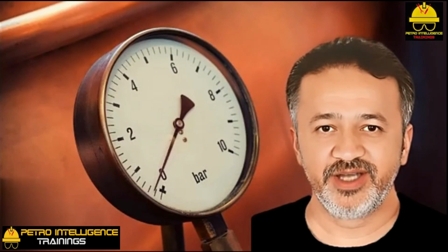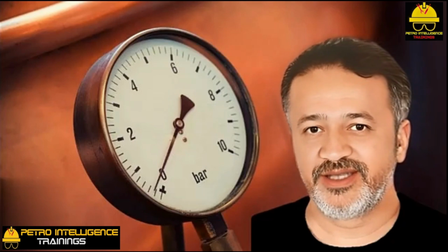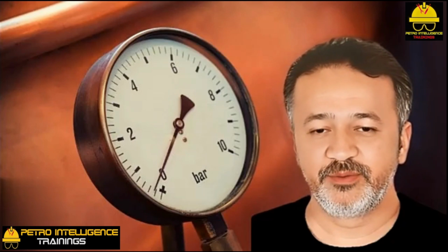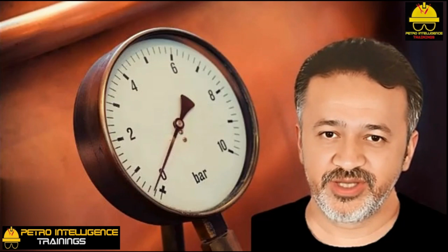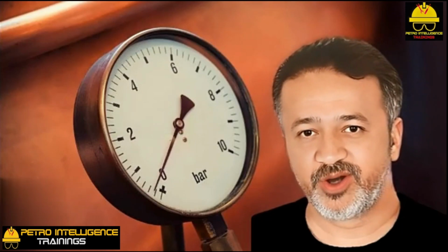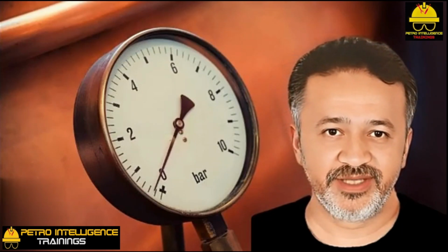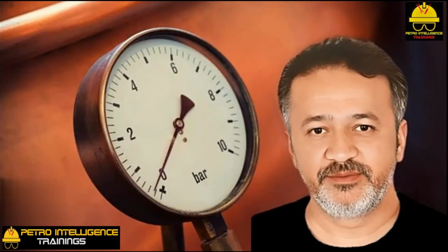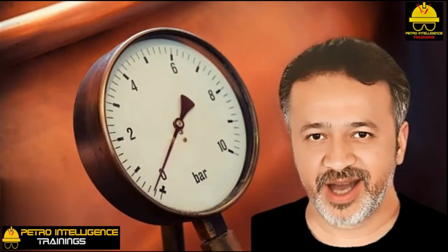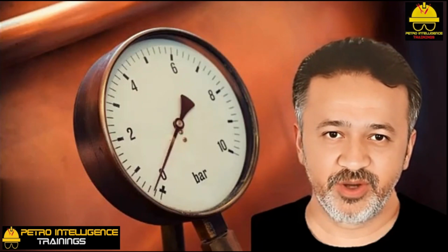Note that there is not a lot of difference between measuring a flow and a level. They both are typically measured by using a differential pressure signal. Naturally, just like level indicators, the flow orifice taps can plug. If the upstream tap plugs, the flow will read low or zero. It is best to blow the tap back with glycol, but that is not always practical.